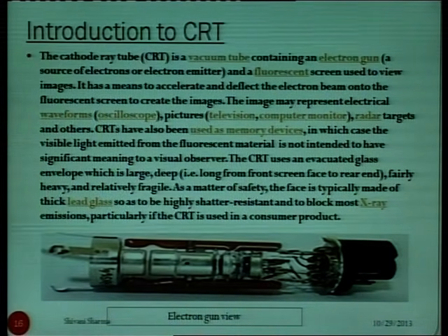Means as a disadvantage, we can say in the CRT monitor sometimes we have some X-ray emission also. So, to avoid or to absorb this radiation, we generally use CRTs which are made up of thick lead glass.